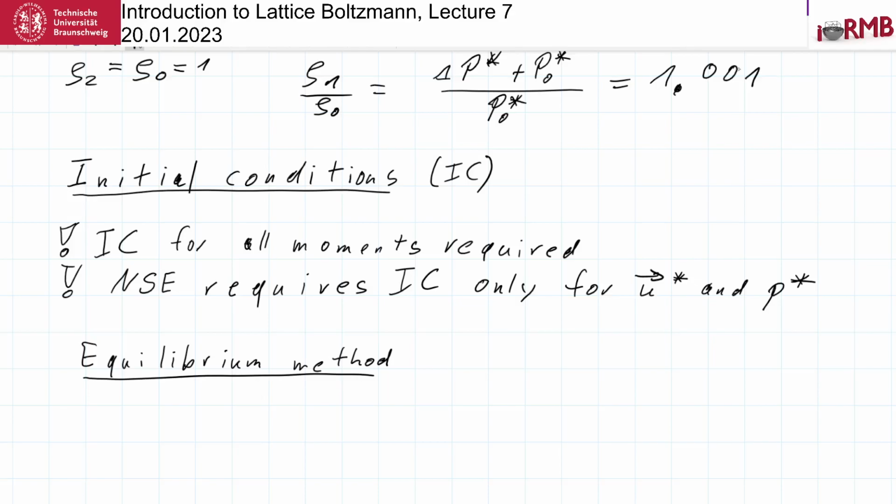So say we are given u of x and 0, so this is the time 0, right? And now a density, which we usually compute from the pressure at position x and 0. Then what we very simply do is compute the local equilibrium that you need to compute anyway for your BGK collision operator, if you are using this.